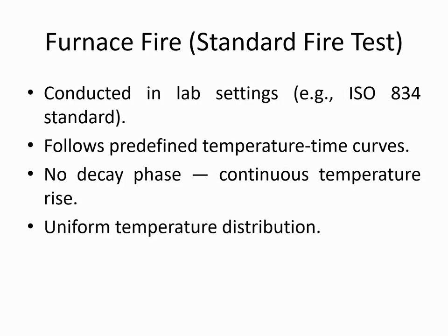After the component fire, we move into the furnace fire. The furnace fire refers to a controlled laboratory fire test such as ISO 834. Here the temperature follows a predefined time temperature curve. Temperature rises continuously with no decay phase.